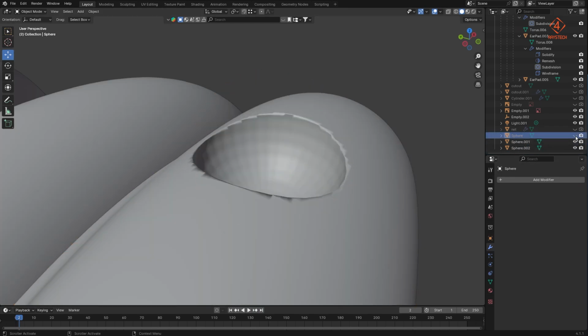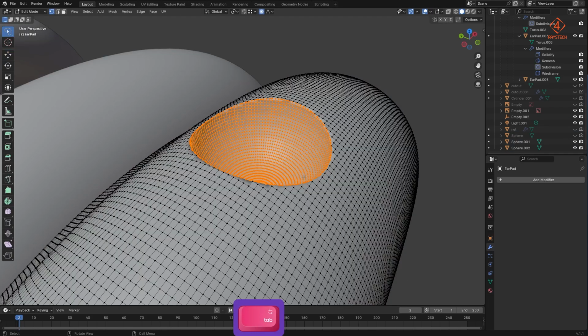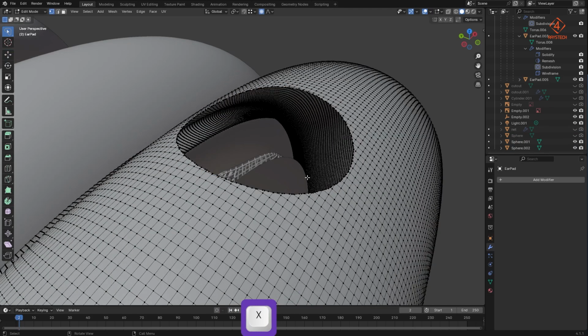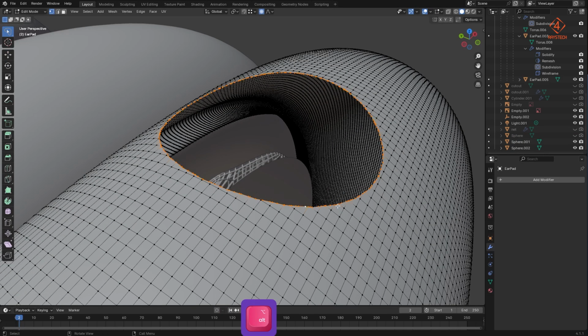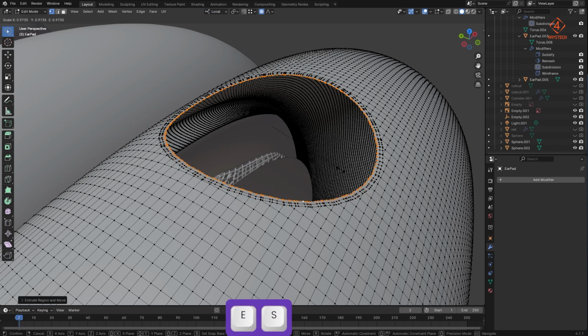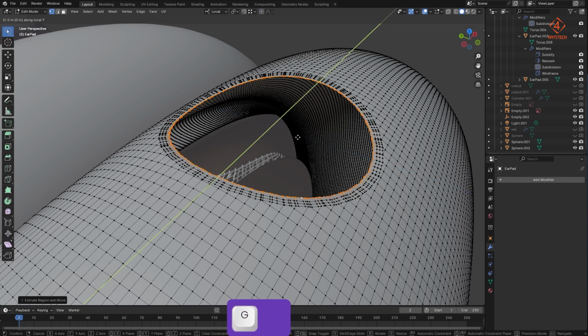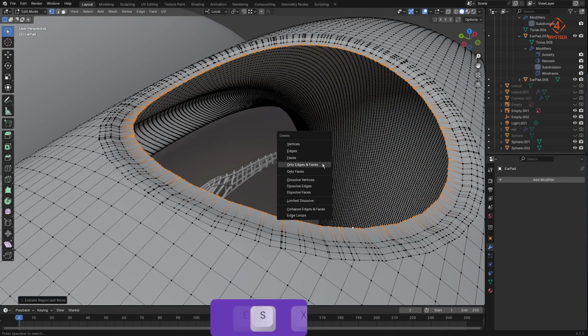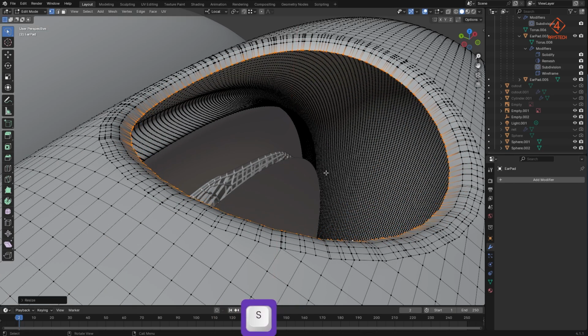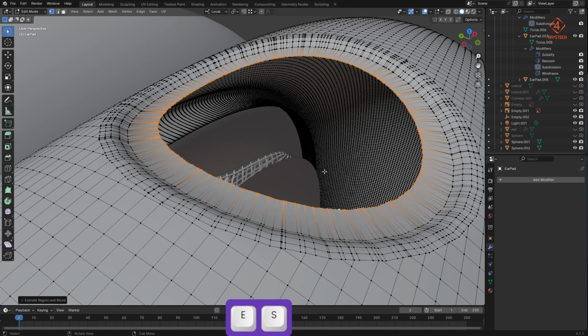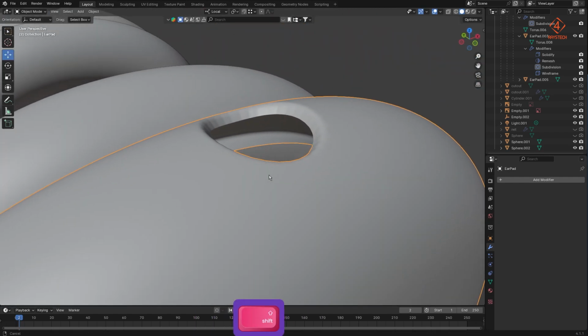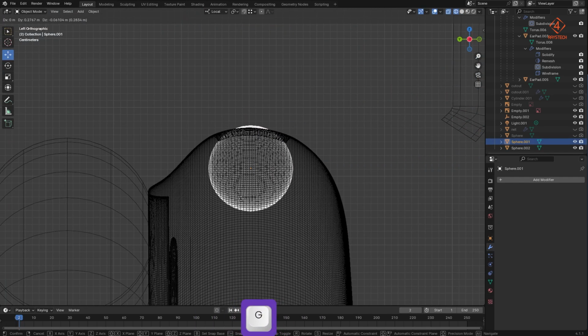So I'm using the same Boolean tool to create this cutout and delete these faces, use the edges. Once again, Alt-click on the edge to select the edge loop and extrude it inside. And then just position it roughly. Later on, as I mentioned, I used a cylinder to make a cleaner cut and Boolean it with a simple cylinder that had a lot of subdivisions on it, so I get a cleaner cutout of this.